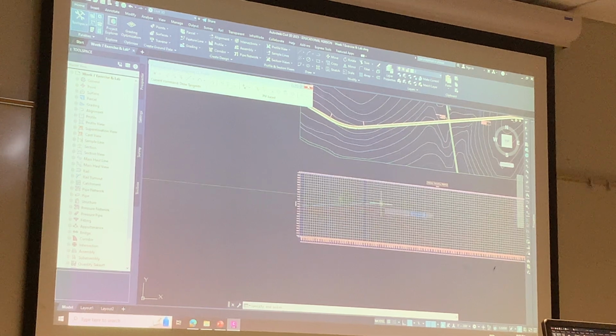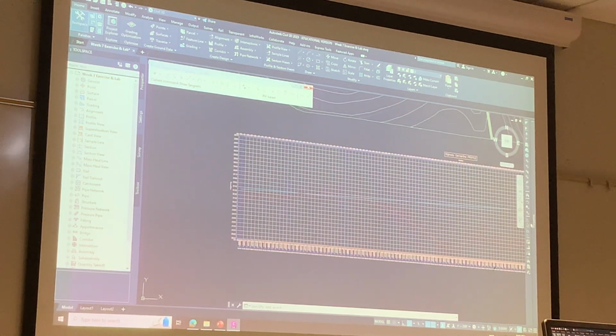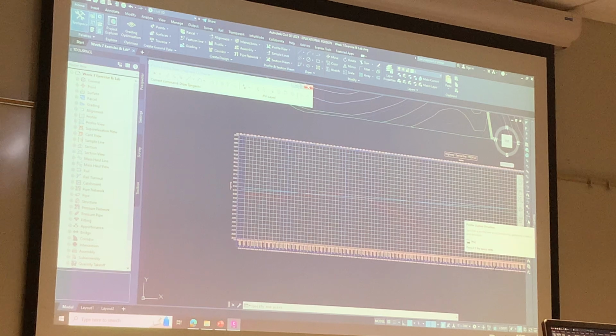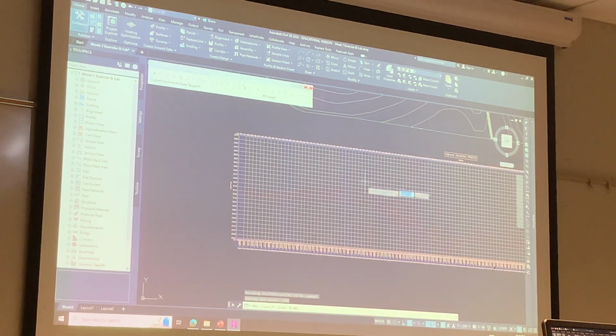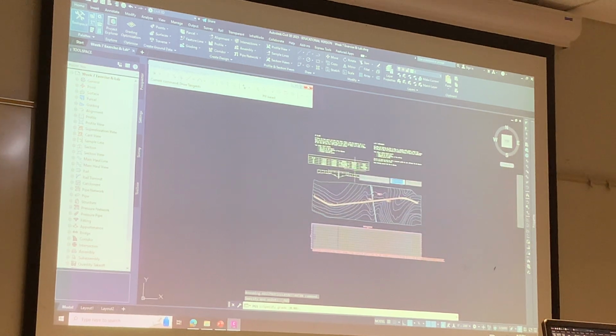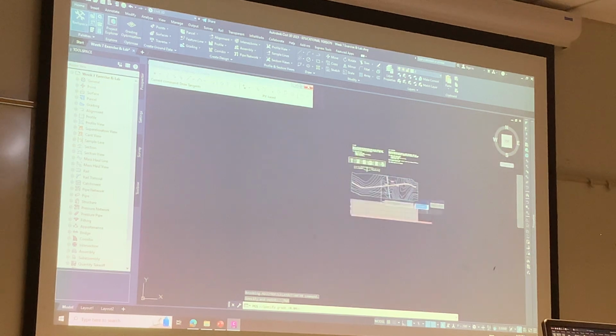So we're now drawing our profile line. My next option after the profile station elevation is the one right below it, profile grade station. I will click on that one. It's going to ask me to specify a grade. What's the grade that I want to start with? It's 0.3, right?